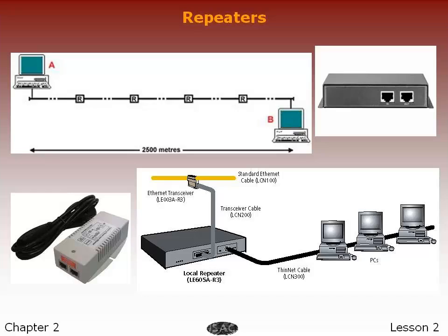An optical communications repeater is a piece of equipment that receives an optical signal, converts that signal into an electrical one, regenerates it, and then retransmits it as an optical signal. In contrast, optical amplifiers, which amplify the light beam directly, are often used in transcontinental and submarine communication cables because the signal loss over such distances would be unacceptable without them.